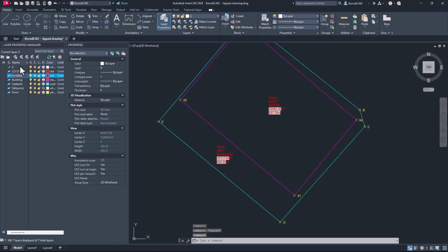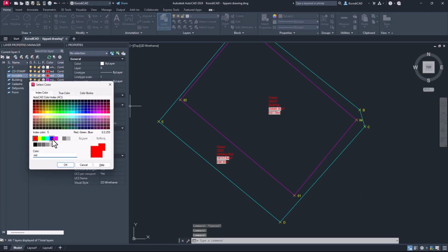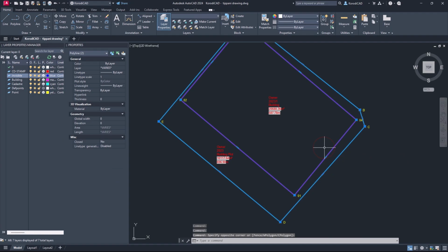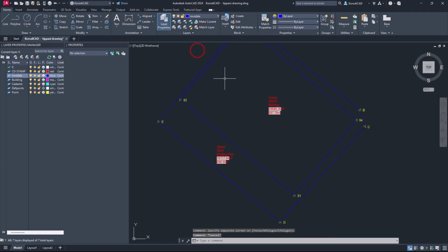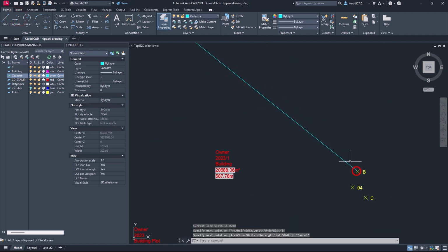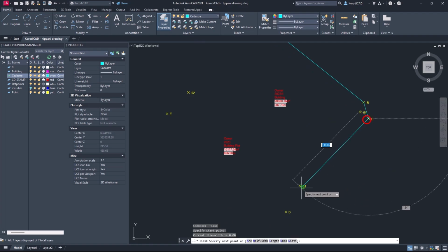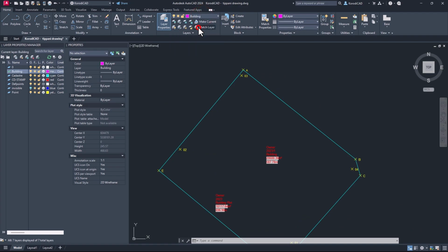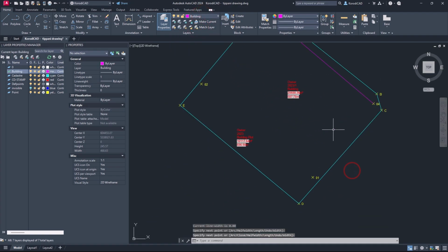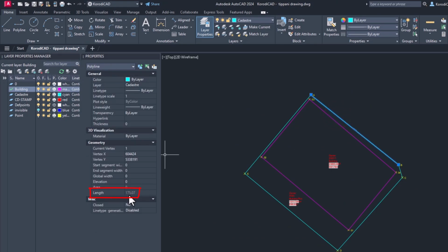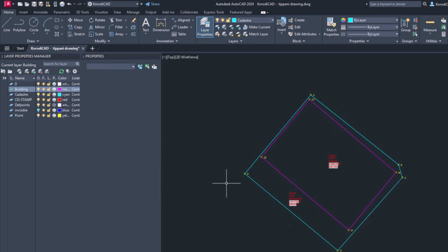We can also create an invisible layer on which we place, for example, source objects. Then, we connect the points with lines or polylines, making it easy to read distances and other geometric properties from the panel, or embed them into fields, as we did with the area and perimeter.